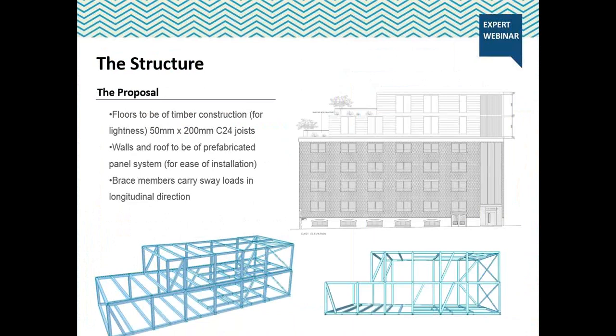We began to develop the scheme within Midas. One of the requirements from the local authority was for the proposed window locations to follow those in the existing building. To ensure this, and to create the proposed flexible 5th and 6th floor plans, we produced a structural scheme aimed to allow full width openings in the south facade and frames that minimize weight. The proposed building is clad with a prefabricated wall and roof panel system.